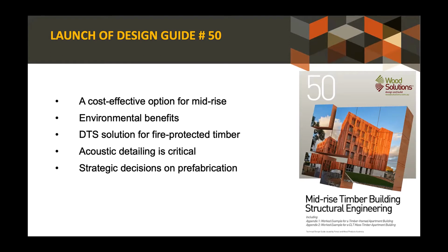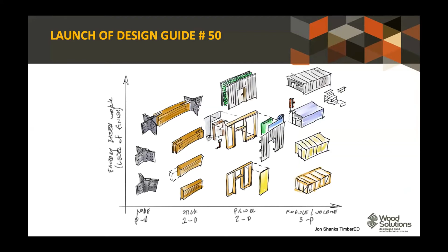And importantly, there's a deemed to satisfy solution for fire-protected timber for buildings of any class of this scale, which is a key one with respect to the fire design and the fire solution. The DTS provides a cost-effective option for satisfying the requirements. Acoustic detailing is critical, and I'll touch on this again and again through the presentation today. And there's actually an opportunity for some really strategic decisions on prefabrication.